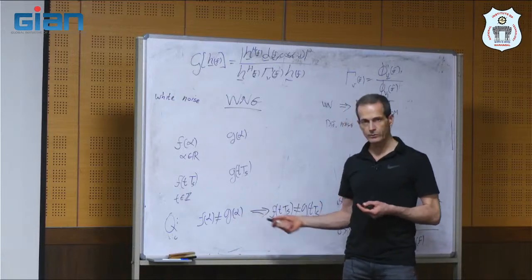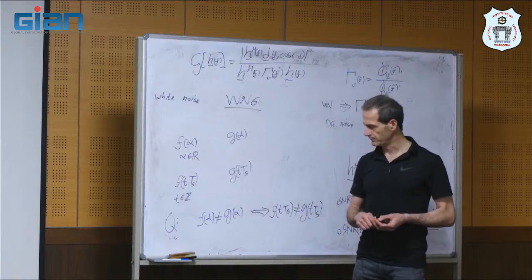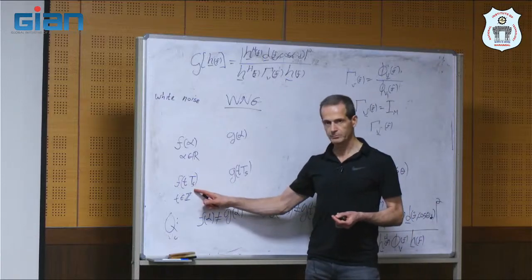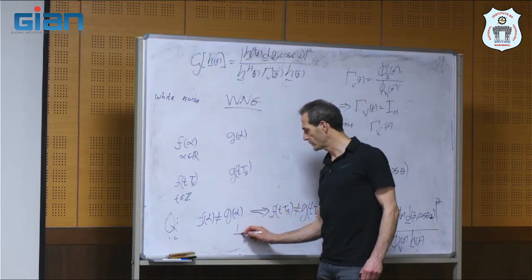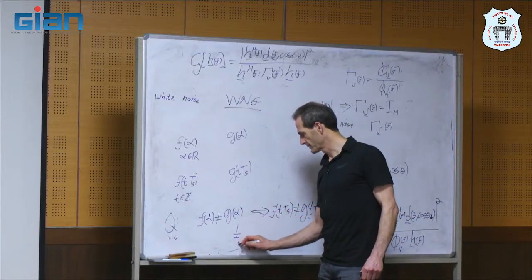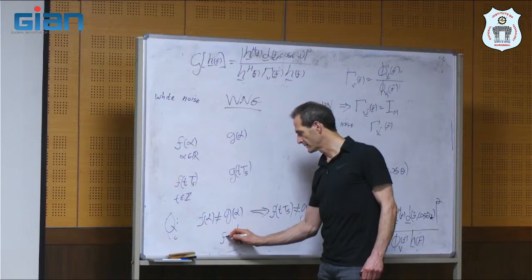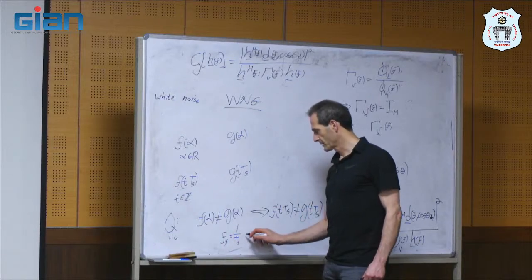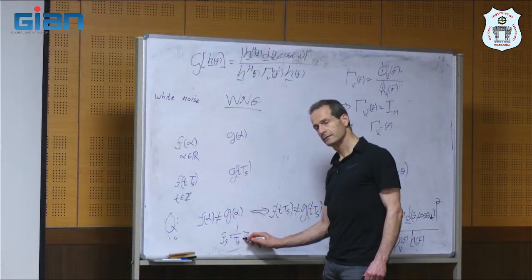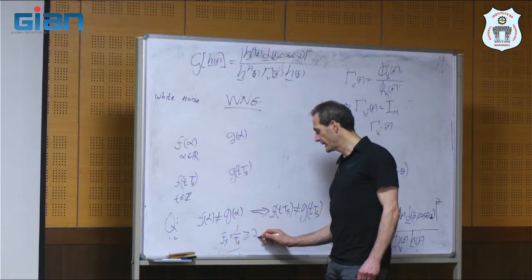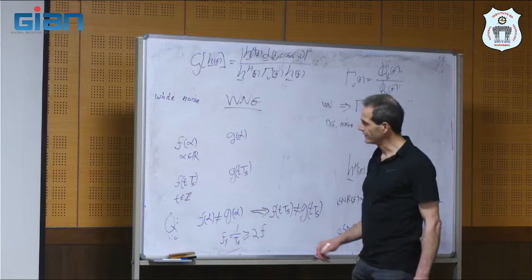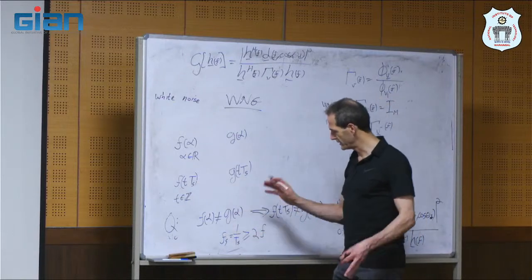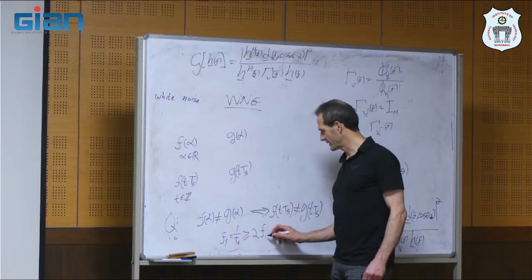So this is the Nyquist requirement on the sampling interval. So the sampling interval should be such, okay, or 1 over Ts, this is the sampling frequency, Fs, should be at least twice, okay, I use F here and F here, so let's call it F max.